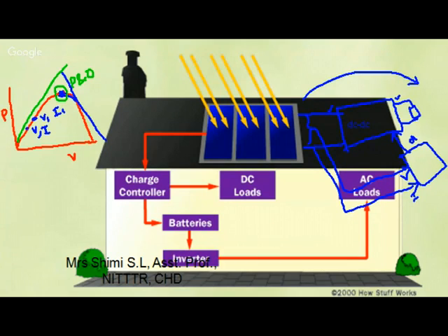Then what will they do? Keeping that point as the base, they use particle swarm optimization, GA, or some other optimization algorithm to again find the global maxima. Those optimization algorithms will help you find the global maximum power point, so to measure the MPPT point you can use optimization techniques also. That is also a field where you can do a lot of research.